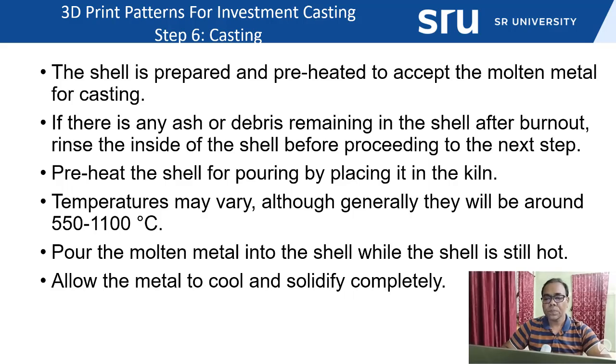The temperature may vary, so you heat it around 500 to 1000 degrees centigrade, and then pour the molten material into the shell while it is still hot. Allow the poured material a certain time period so that proper cooling and solidification take place.